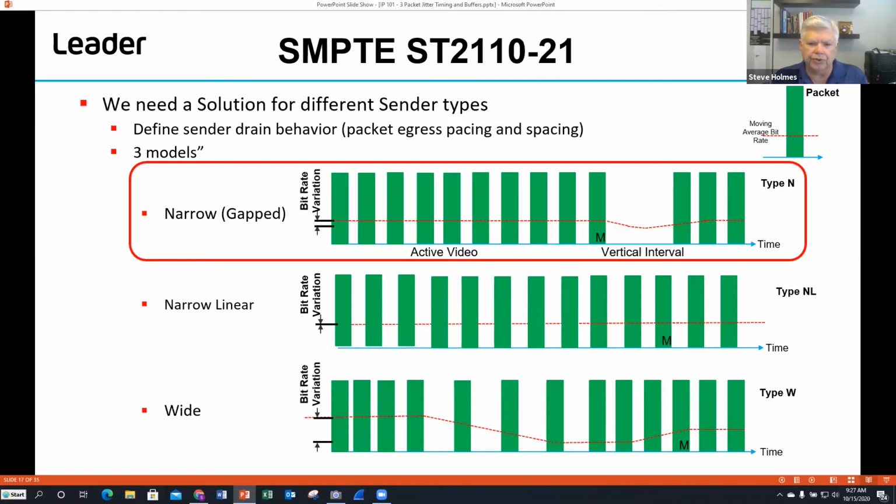And this really brought some new stuff up when they first started putting these out, because there were a lot of receivers where they'd take a software sender, plug it into their network, put it into a conventional receiver, and get absolutely nothing or get trash out of that particular receiver, because the data was varying so much they didn't have enough buffer in the receiver to be able to handle what was going on.